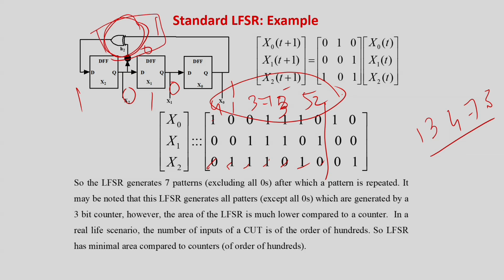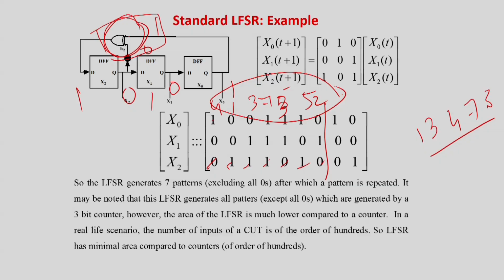It will be quite a large circuit. Just by looking at the digital design fundamentals, we can find out how to design such interesting counters, like up and down counters, particular sequence generators. So it is never a single gate, it's a large bunch of gates. For 3 bits, only one gate is doing it. Very interestingly, in case of LFSRs, as we will see, even with a very high increase in bit width, the number of XOR gates required will not be very high. But if you are going for a predetermined pattern generator sequence, using digital design, finite state machine based optimization, it's a very, very large hardware. Maybe hundreds of gates will be required for a 32-bit input or something like that. So here the saving is huge.